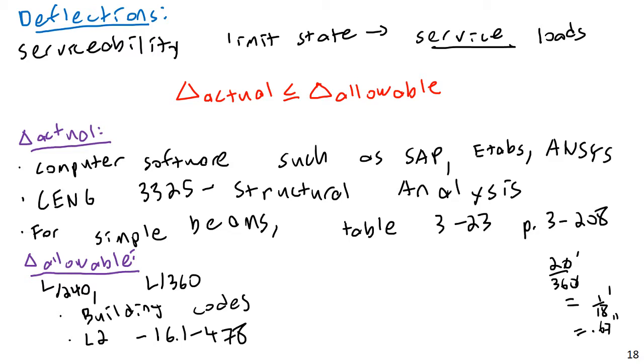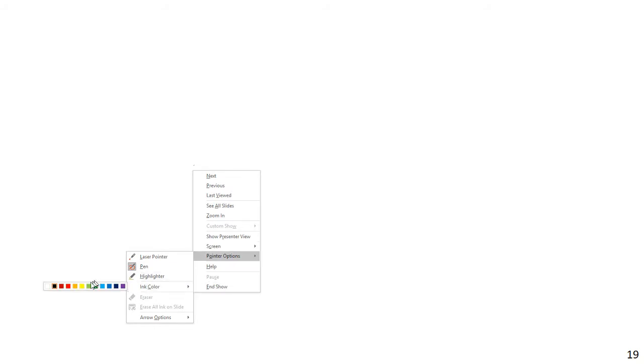So that's the basic idea for deflections. Unlike concrete beams, where we'll have to look at deflections a lot more, for steel beams it's relatively simple. However, though it does seem relatively simple, deflections often actually govern, especially for steel structures. Deflections often do control.